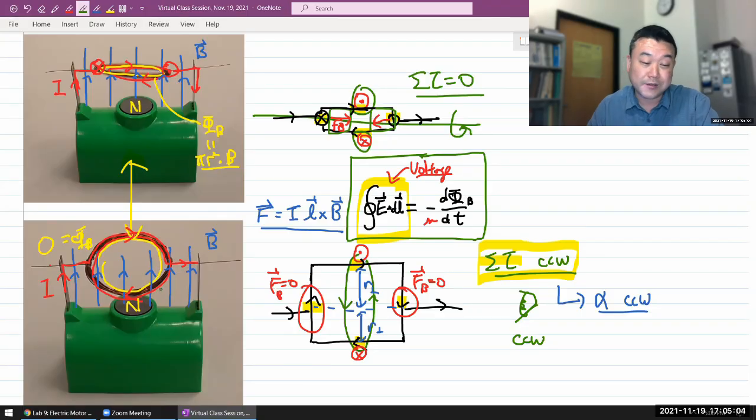While the motor is running, it's perfectly safe because this induced voltage will oppose the applied voltage, limiting how fast it can spin and how much current it eventually draws. So okay, that's the lecture on electric motor that we really had to hold off until now so that we can discuss the full detail of everything that goes into operation of motor.